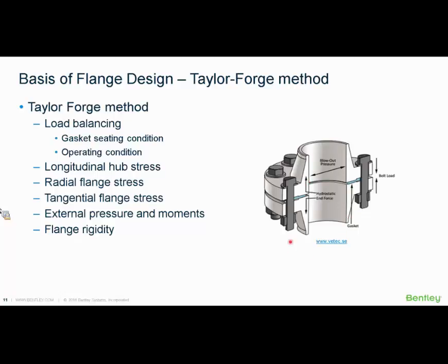So if you look at this diagram, if you start bolting it up, the gasket would start to experience a force that would be equal to what the bolts actually exert in the other direction, right? This is for the gasket seating condition, and these loads would need to be balanced out.